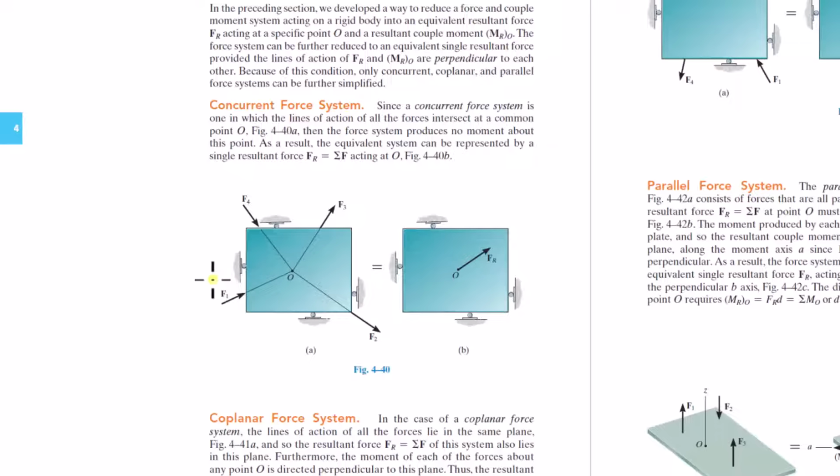All of the forces acting on a body in static equilibrium meet at a point, and you can draw the free body diagram as just a point with all the forces acting on that point, and then you do a vector sum, get the resultant vector, and place it on that point. Now, we did talk about how, if that point is the center of mass, then for the dynamic or the static case, you can use the particle free body diagram model. It's that particle model. If it's not the center of mass, if it's static equilibrium, you can still use the particle model.